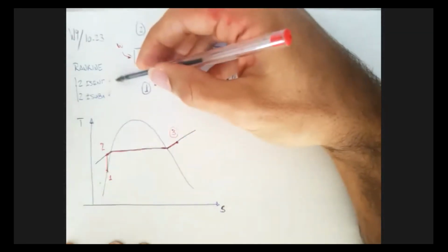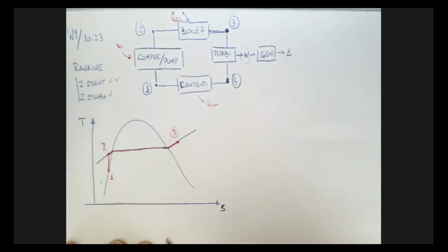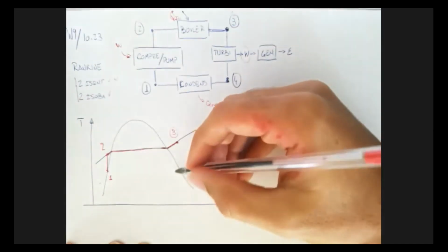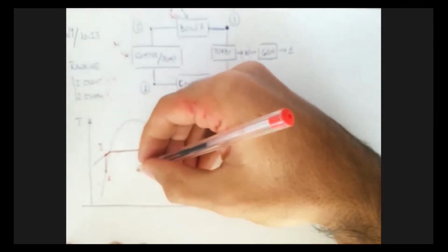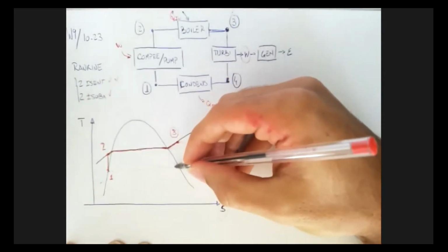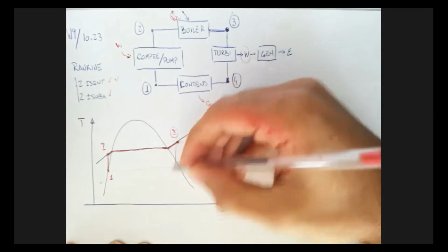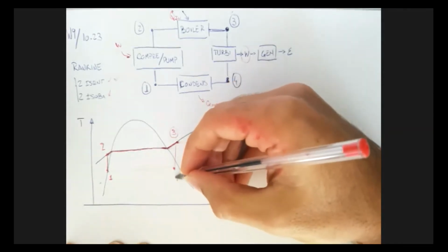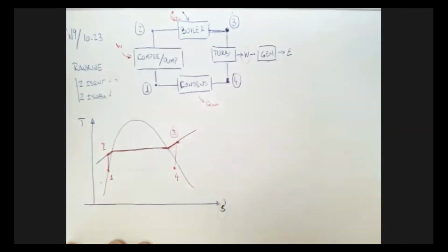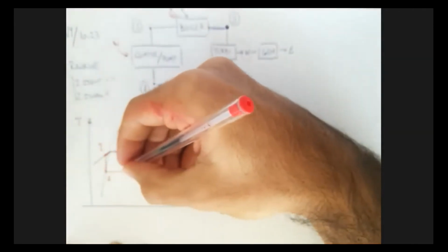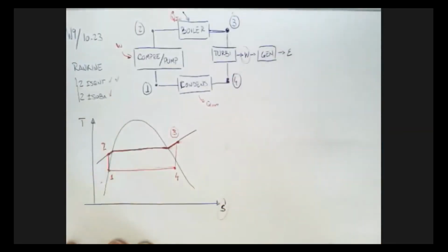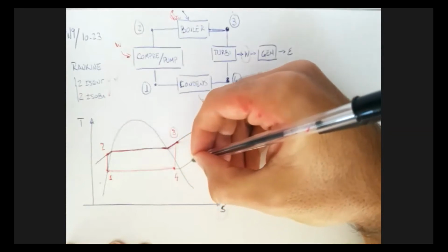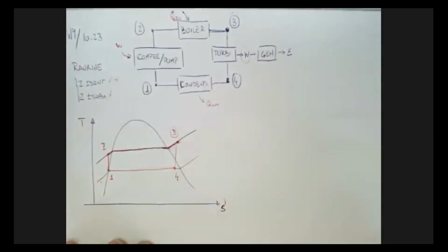Now we have another isentropic process, going down, so no change in S. We go straight down to our state 4, and I stop there because I know it's going to be another isobaric change from 4 to 1, so it has to be on the same line because of the saturation line once again. The saturation line will go down like this. So that's our cycle right there.